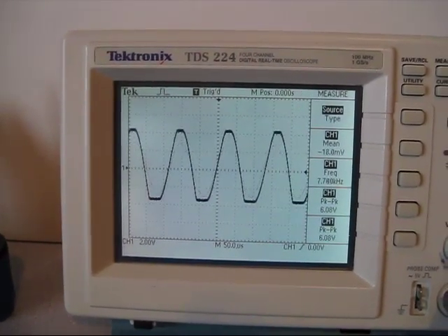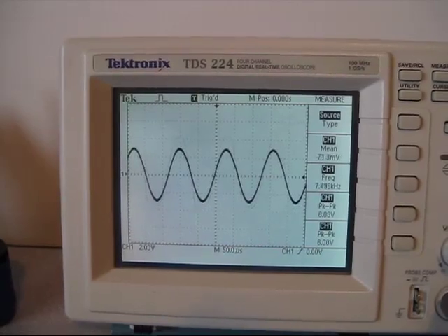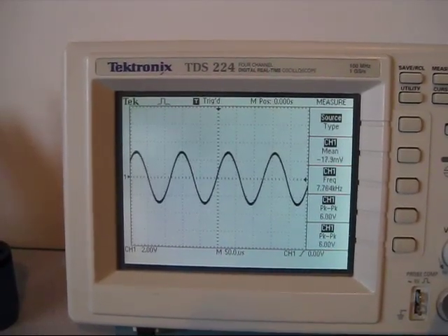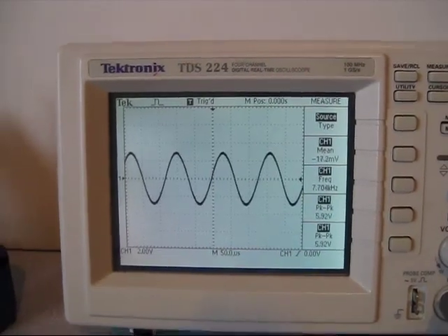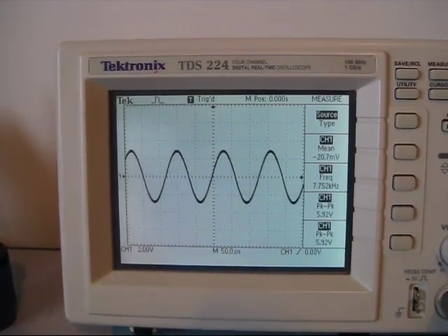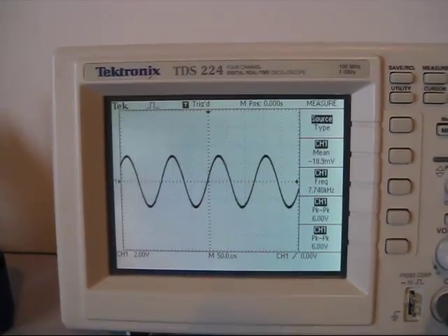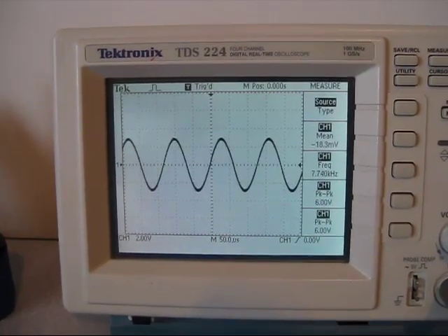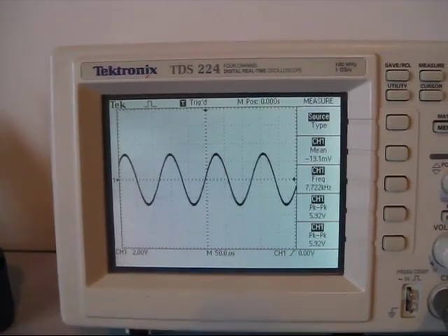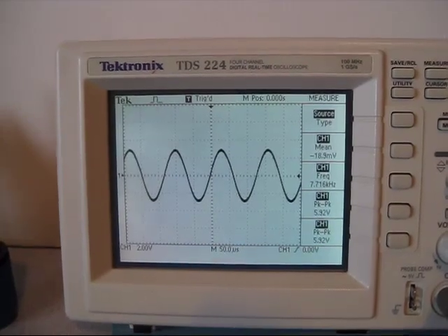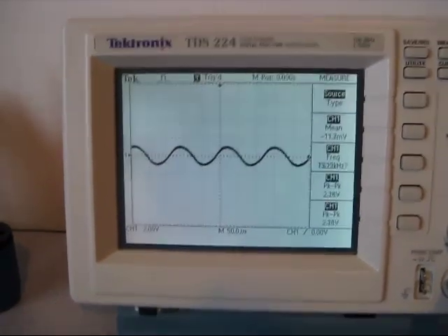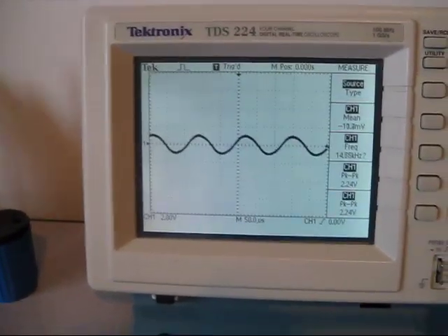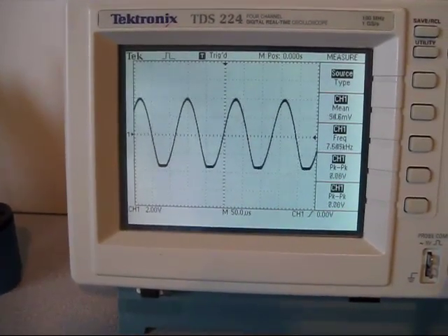So that's with it, without it. See, that's why you need that. Even if it is just affecting the gain just a little bit, that little bit is still necessary to make it look all right. So ideally you would then take this, buffer it, and you'd probably want to still filter it, but pretty good. So if I just bypass that completely, and I'm just using the pot, right, you can see we've got quite the range.